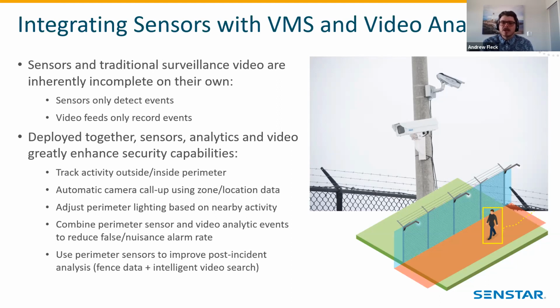Now, what they do, though, is they don't declare that an alarm. What they do is wait for the LM100 to actually activate, because the LM100 has an accelerometer built into it. It is a perimeter sensor and it is a light. It is not a motion detector. So we do need to use video if we want to look for motion. That's the one thing I do want to convey to everybody: there's no motion sensing capabilities in the light whatsoever.